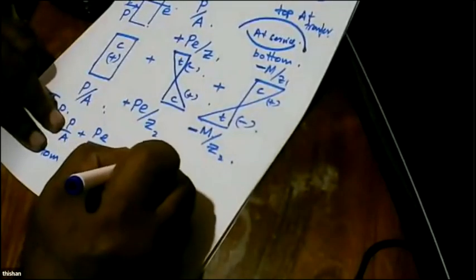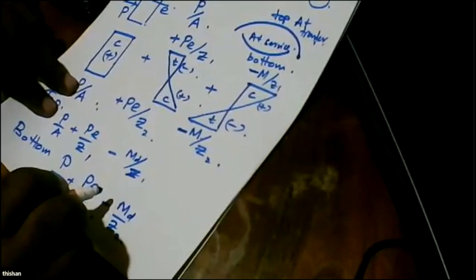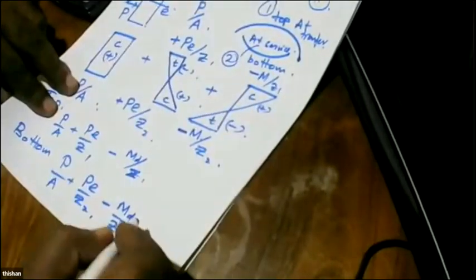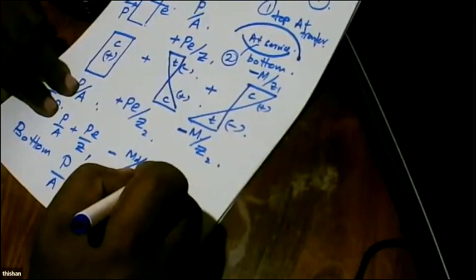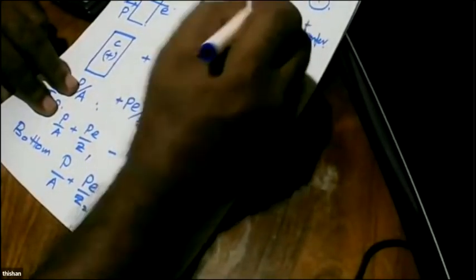So at transfer, what you get is only the dead load. And when you have only the dead load, it is this situation, that is situation number 1, this is situation number 2. So when you get situation number 1, the top fiber can fail in tension.